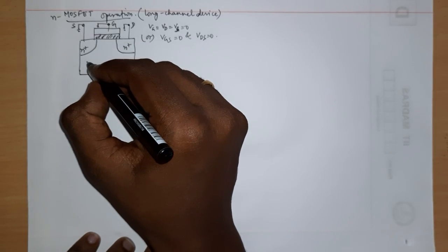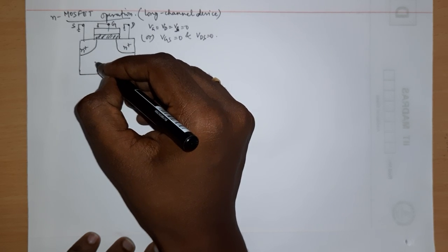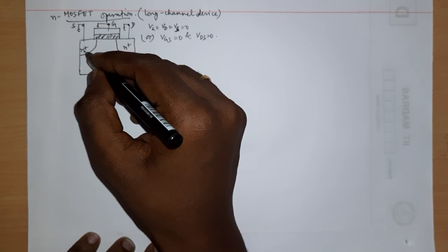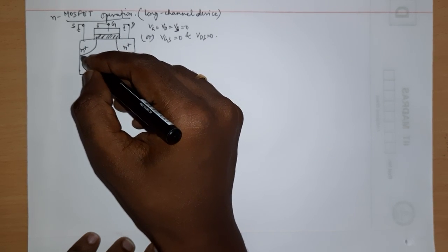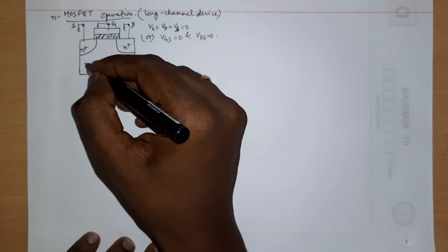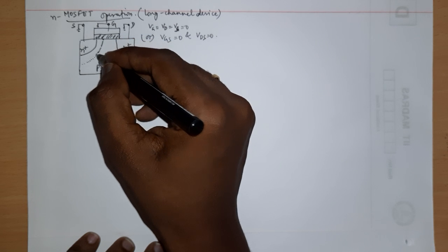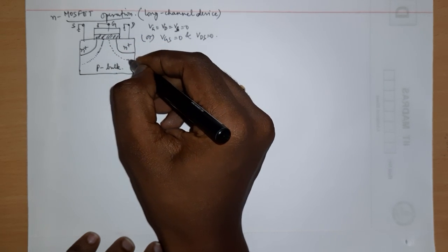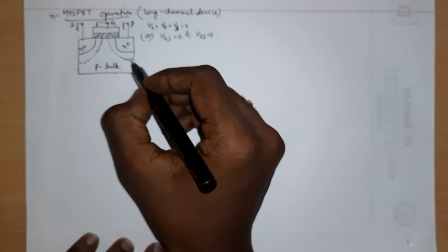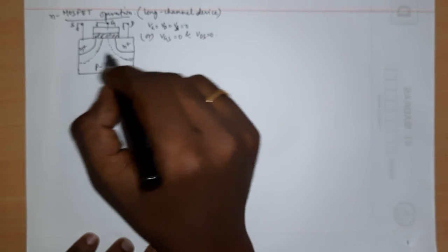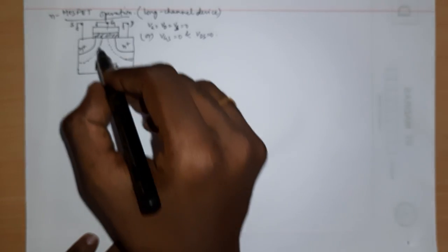So in this case, first of all, it's a PN junction, so there exists some kind of a depletion region. And this is an N plus junction, which is heavily doped compared to the P, so you have more of the depletion region extending towards the P side rather than the N side. So let me just draw the boundary of the depletion region, and here also it is equally spaced. There can be some asymmetry in my drawing, but it's basically symmetric on either side.